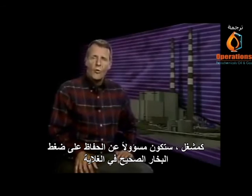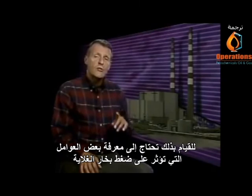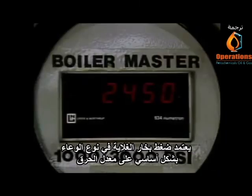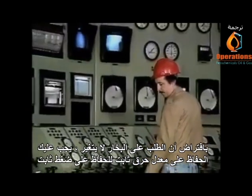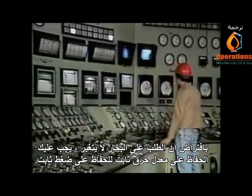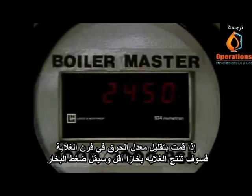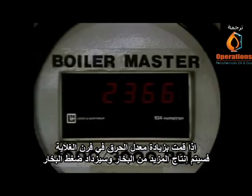As an operator, you'll be responsible for maintaining the correct steam pressure in your boiler. To do this, you need to know some of the factors that affect boiler steam pressure. In a drum-type boiler, steam pressure depends primarily on firing rate. Assuming the demand for steam doesn't change, you have to maintain a constant firing rate to maintain a constant pressure. If you reduce the firing rate in the boiler furnace, the boiler will produce less steam and steam pressure will decrease. If you increase the firing rate in the boiler furnace, more steam will be produced and steam pressure will increase.